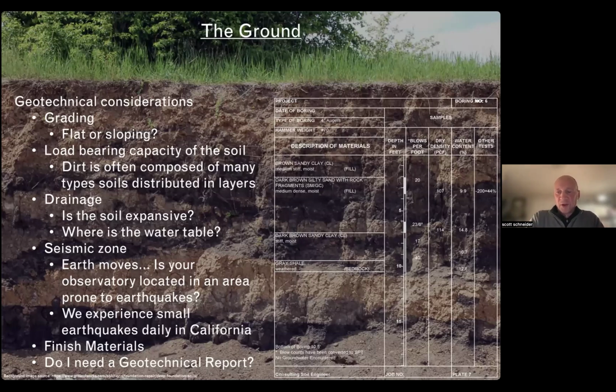Freezing and thawing can also impact the foundation, and of course these silty types of soils are not great for that either, because if they can absorb water, they can freeze, and then when they thaw, they also move a lot. And it can actually cause your foundations to crack.